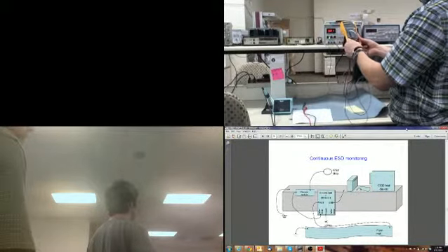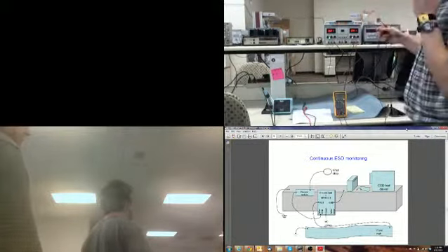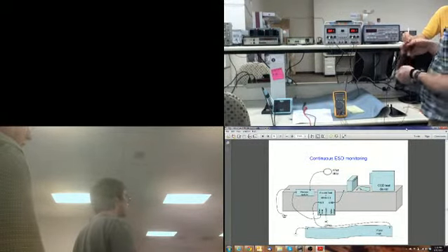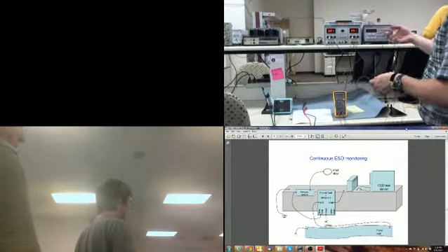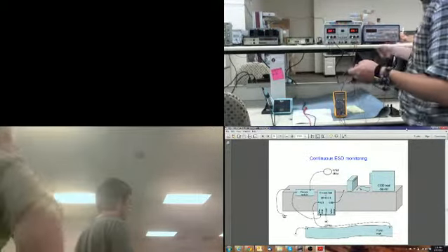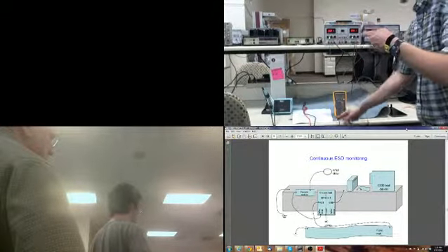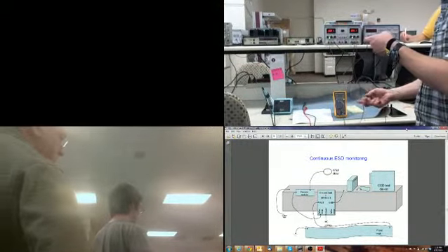Okay, now this thing is set up to read current. For current, I talked about it being a through variable. You have to force the current to flow through in a circular loop. It may be hard to see, but the current is going to flow through the black lead, through the common, out the A. That's just so the polarity will be right.